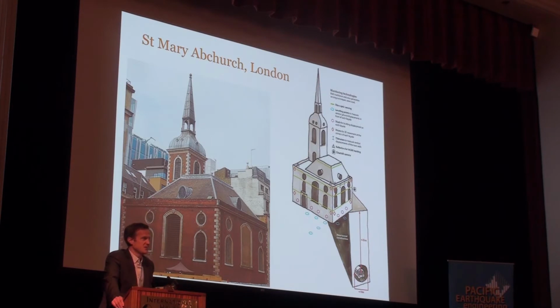And the reason we want to do this, and this is the critical advantage of fiber optics, is that you can measure distributed strain quite well. We don't know exactly where the damage is going to happen, and so it enables us to measure damage over a very wide range of areas within the building.